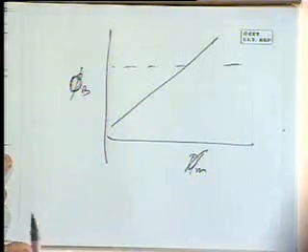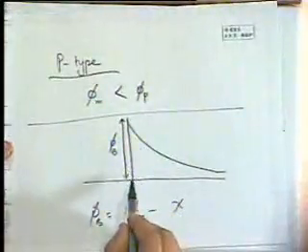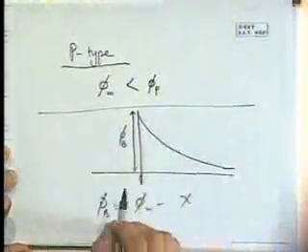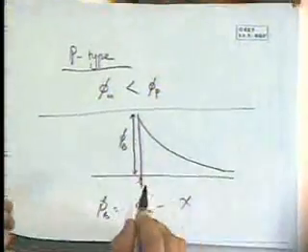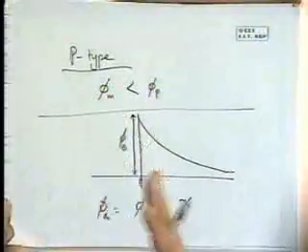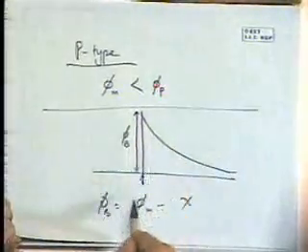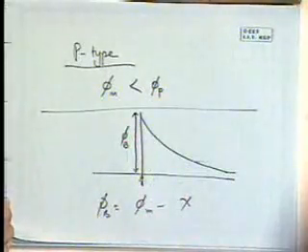And there are many theories related to it, but basically the idea is that due to what are called surface states and defects, that means there are some other levels here which we haven't even thought about. We're talking of a perfect metal semiconductor interface. There are other defect states introduced here which effectively pin the Fermi level to some value.